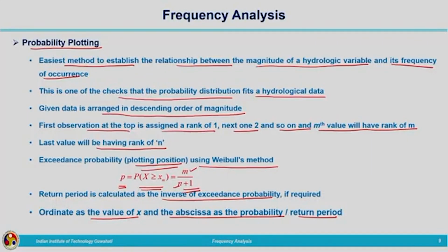By making use of this particular technique of frequency analysis, we can find out the magnitude of a particular event corresponding to a certain exceedance probability and the magnitude corresponding to a particular return period. These can be obtained by making use of this frequency analysis. Here I have explained about finding out the plotting position by means of Weibull's method.